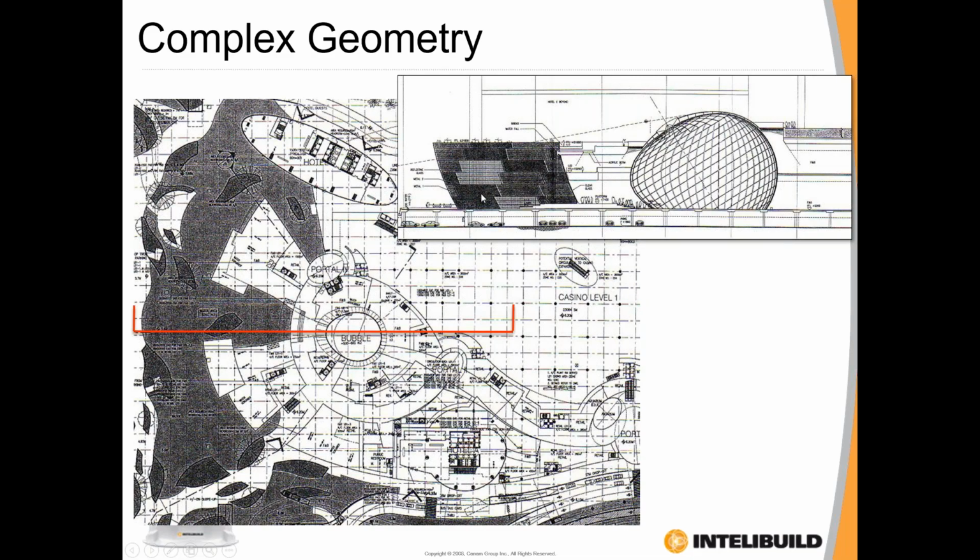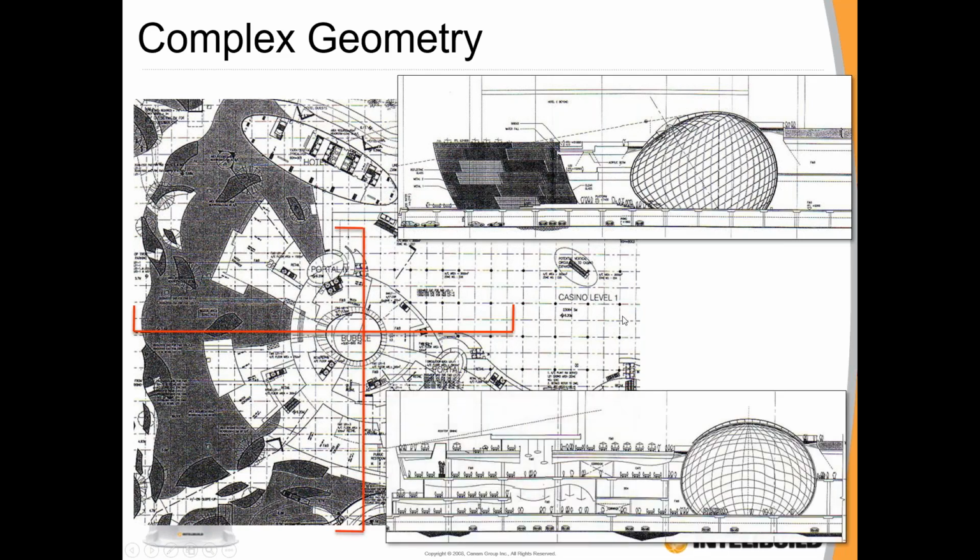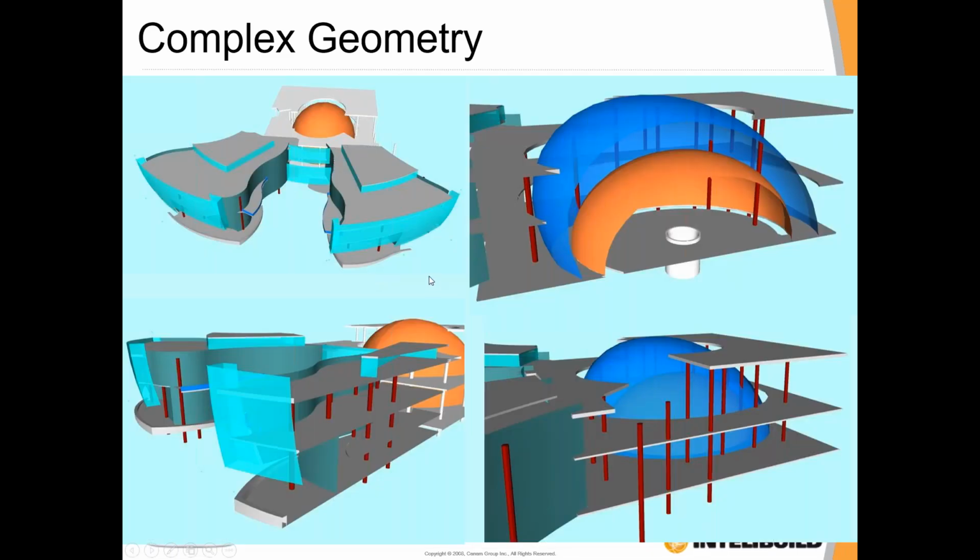When you cut a section through it, you can see the external elevation, you can see the basement car parking, and you can see the complexity of the shape. So in order to design and construct this, we had to use parametric modeling. Now, parametric modeling is rule-based modeling, so if you make changes to certain features, the whole model will change in relationship. So this is an initial geometry model in Rhino.